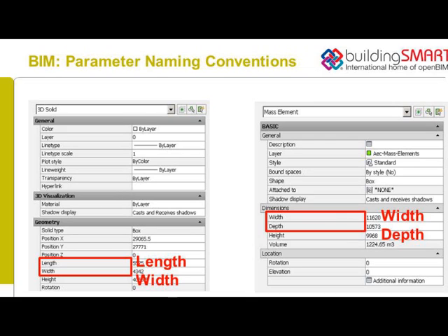Revit, as you'll probably know, is case sensitive on the parameters. So whether you start with lowercase, uppercase, whether you misspell it, you add your bits or whatever, they're all different parameters. Something basic, simple in terms of description: if somebody's added description from different shared parameters files or different content, you're going to get multiple description parameters, as Glynis mentioned, and other things in your models.